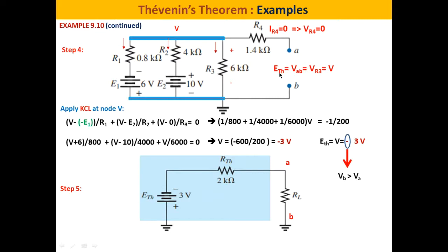Here we have to calculate E Thevenin with the polarity. The sign of the result will give us the polarity of the voltage supply that you have to use to represent the Thevenin equivalent circuit. So let's apply the nodal analysis technique that you have learned in previous weeks. So let's identify the different nodes. We have 2 nodes. This node, which is chosen to be the reference, and we have the node V here. This point and this point are known because here we have E1, E2 known.